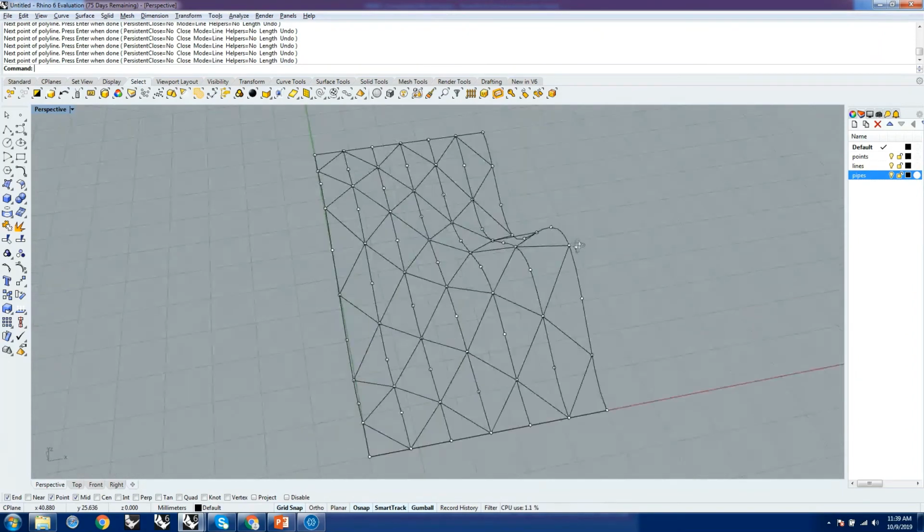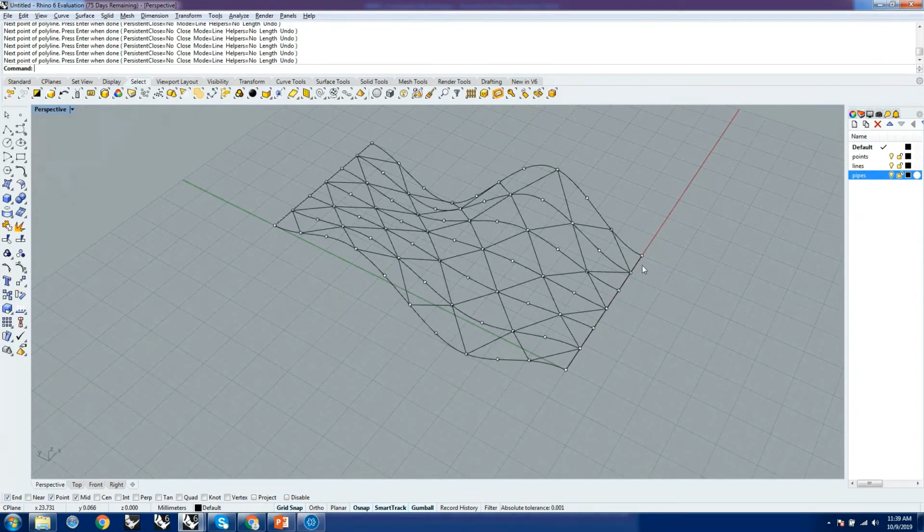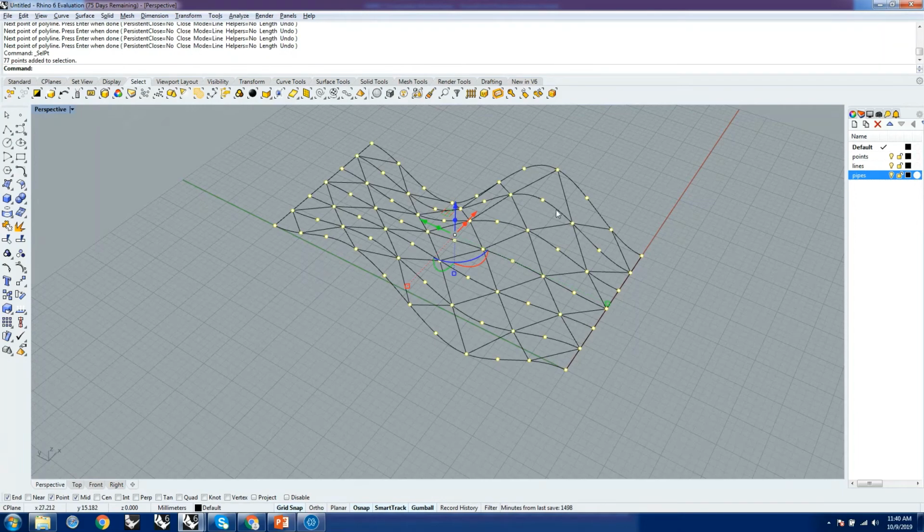Okay, now are we going to select all these lines individually, these points individually, and then put them into these? No, we're going to use Rhino to help us. So I'm going to type select points, underscore SELPT. And as you can see, the moment you type select, it gives you a plethora of options of what exactly you want to select, how you want to select it, by layer, by color, by block, by whatever. So I'm going to say select point, and it selects all the points.